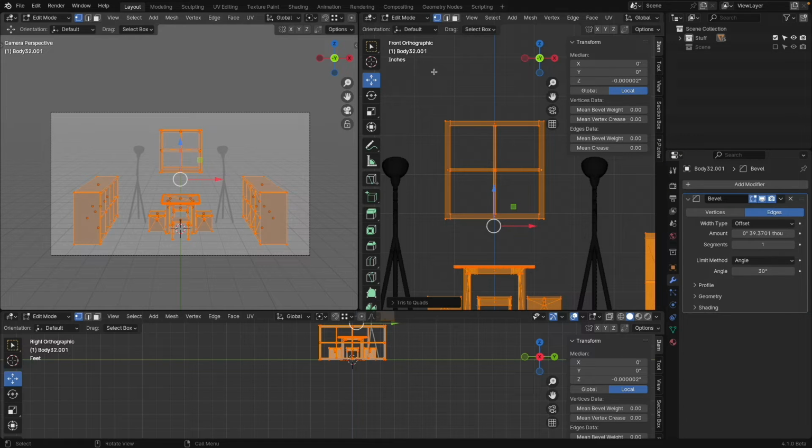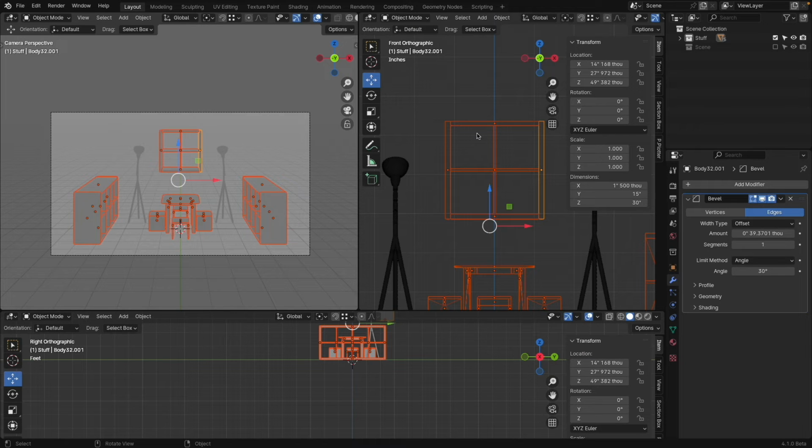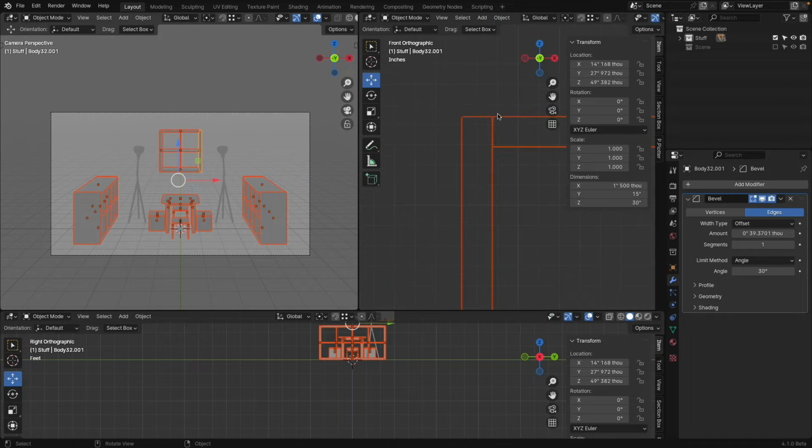It's now actually a quad. And in most cases, this bevel command now works better. And this goes back to when in Fusion I said like we don't need to fillet these edges for chamfer. We can do this in Blender as a modifier. Less geometry to import to animate. And we still get the same result. Pretty cool. Okay.